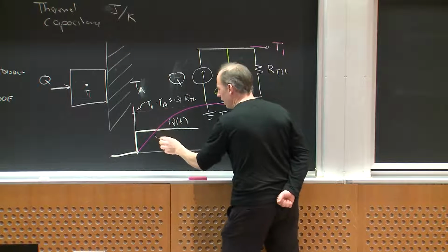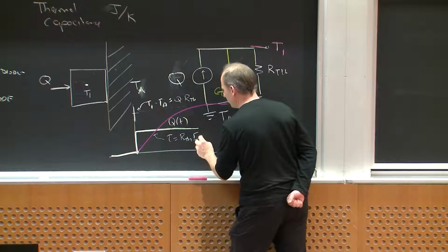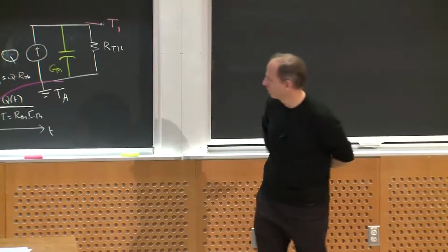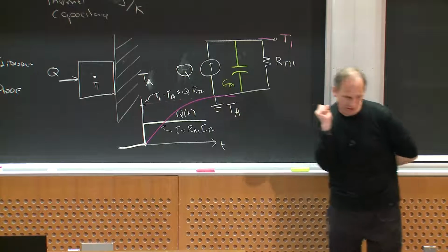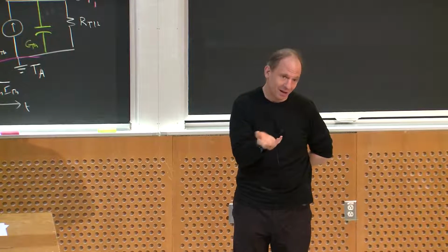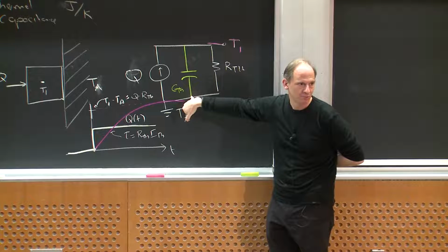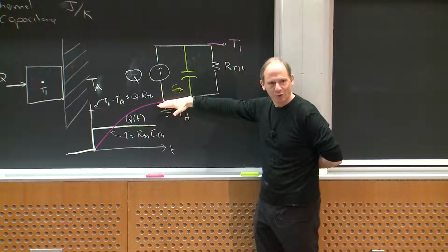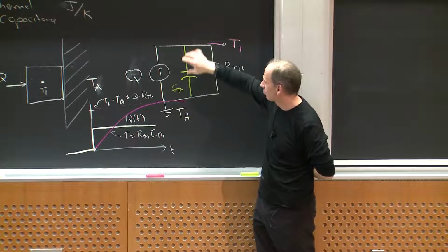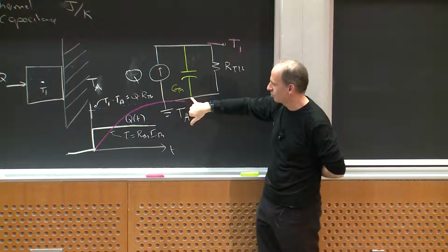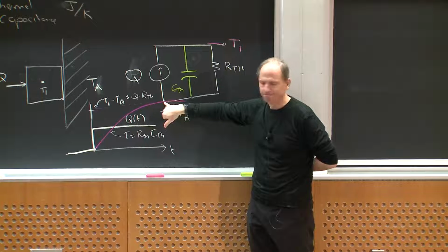That's its final value. And it's going to rise with a time constant, tau, that's equal to RTH CTH. So it won't immediately get hot, it'll just rise over time. Now I should say, fundamentally, a thermal capacitance should technically always be referenced to absolute 0. If I'm just dealing with some ambient and I want to call it an offset, I can reference it to a fixed temperature. But in terms of modeling the physics of them heating up, I always have to have that thermal capacitance to my reference point, which would ideally be 0 degrees Kelvin. And I'll come back to that in a moment.